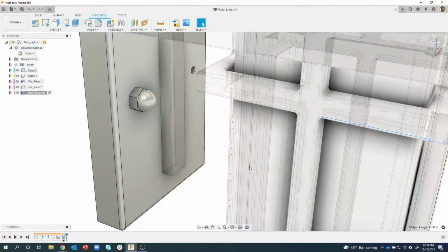Now you might ask, well, wouldn't you use a joint command to do this? Absolutely, you could. But we have a free move, basically. When I inserted it, it's allowing me to move it. So why not move it where it needs to be in the first place? And then you're going to see we're actually going to capture or create what's called a rigid joint. Because they're all where they need to be, we'll capture them as rigid joints. So you'll see that here in just a second.